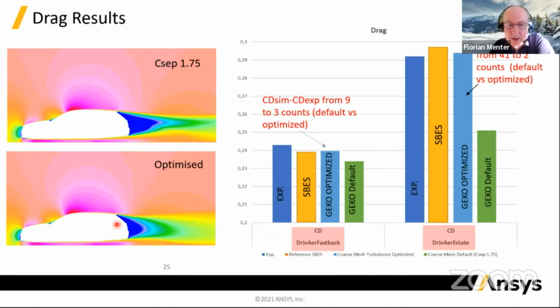And you would imagine that happens because it's less of an aerodynamic shape, and it has more wake influence, and the wake is, of course, with RANS typically overpredicted. So we get here a very close agreement with the experimental data using that optimization. And it's a fairly simple thing. And I personally think that when we talk about optimizing turbulence models, it will be exactly this type of optimization. It will be, I think in English you say, horses for courses. So you're probably not very successful in getting much improved generalized turbulence models, which are much better for any application.